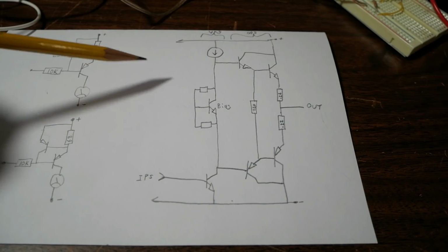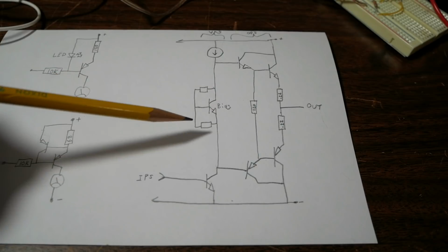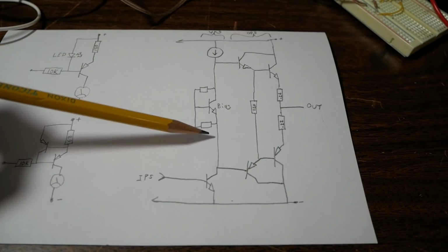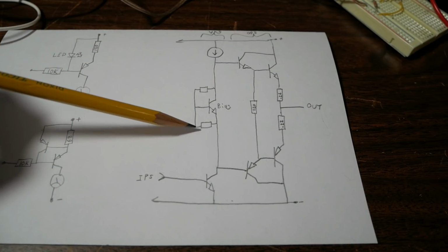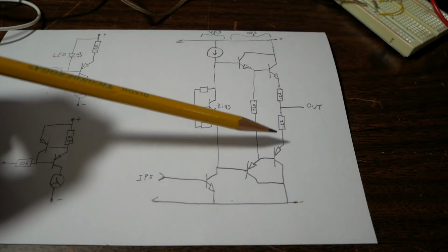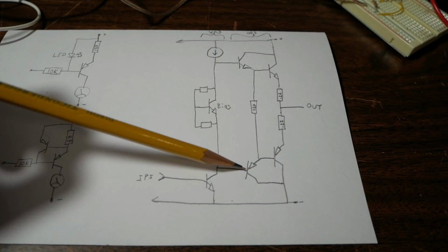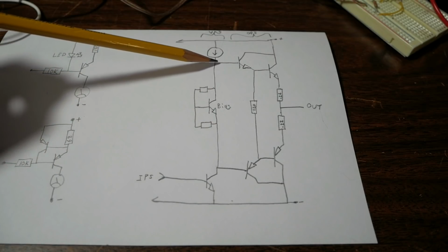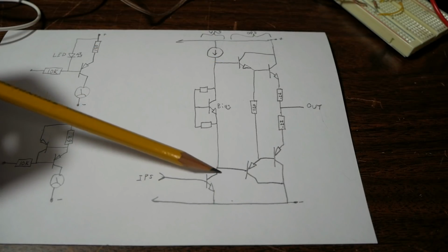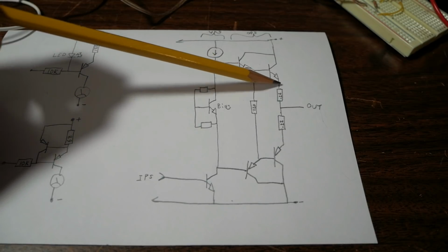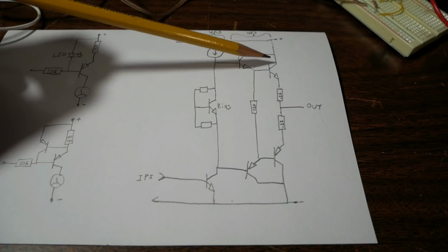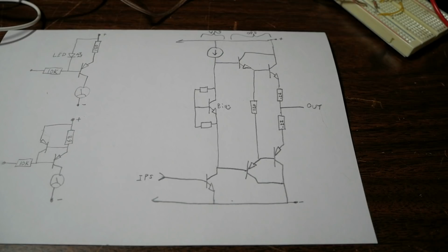The second function of the VAS stage is the biasing network. Some people might consider it a separate circuit, but because it's in the current path of the VAS stage, I consider it part of the VAS stage. So what happens is you have the base emitter junction diode drops around the circuit here. So you need a circuit that sets the voltage at these base points, the upper transistor driver base and the lower transistor driver base. Set that just enough to let current flow through the amplifier like this, which turns the output stage on with a bias. And you do that to eliminate crossover distortion.